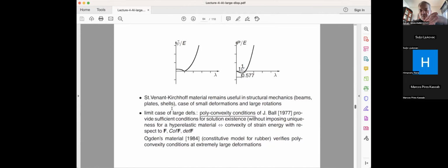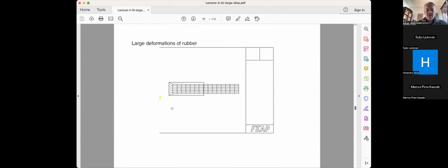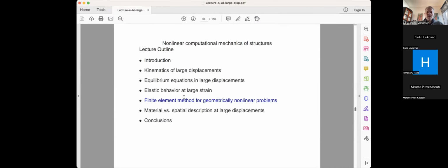And then you can actually work out this systematically for many other cases in terms of principal stretches, but again, this is the work that was already advocated in Hill, only in the notes of the course, but never got published in that sense. So we were developing many of these things. For example, this is large deformation of rubber. This is something like an incompressible material. So the deformed configuration, which is basically stretched 2 times with respect to initial configuration, the volume should be the same as the initial configuration here. And that's basically the one that they can apply.